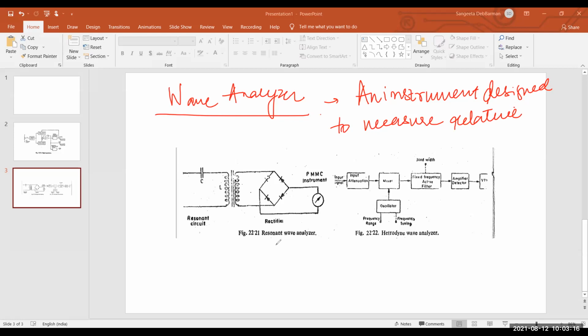Basically, the instrument here acts as a frequency selective voltmeter, which is tuned to the frequency of one signal while rejecting others. So what they actually do is accept one signal and reject other signals. The desired frequency is selected by a frequency calibrated dial, to the point of maximum amplitude. The amplitude is then indicated either by a suitable voltmeter or a CRO.